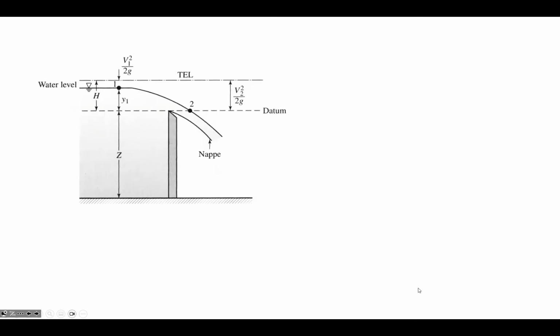So these broad-crested weirs are one way to quantify flow. A sharp-crested weir is another. This sharp-crested weir is different in the sense that we're not necessarily trying to cause critical flow over the obstacle. It's just an obstacle that has caused pooling upstream that ordinarily wouldn't have been there. And what we can do to figure out the relationship between depth, H, and the flow rate is consider the energy before the drawdown occurs, here at location 1, how much energy there is.